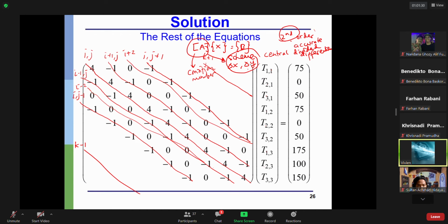And usually if we have a more complex scheme, for example a higher order scheme, the condition number increases. So usually the system is more difficult to be solved, or more difficult to get a low residual, for example if you do the calculation in Gauss-Seidel, because when we change this value, we change the condition number or the coefficient matrix itself.